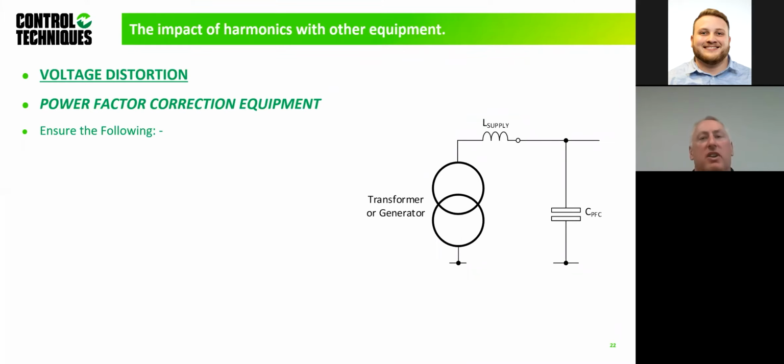So I put a little bit on the power factor correction here, because we've got it on our system there. Again, don't forget this guy. Okay, you just put a drive on the system. Is there power factor correction on your plant, sir? Yes. As it is, can we look? Is it a potential resonant path for these harmonic frequencies to resonate?